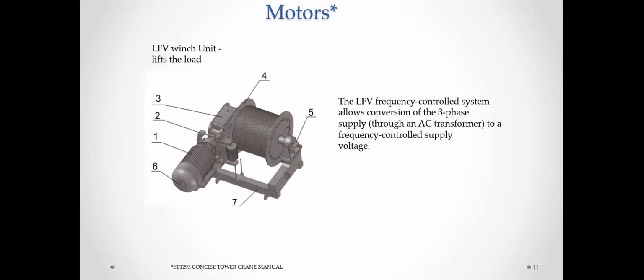Now one of the questions is which DC motors are preferred for the cranes by the manufacturers, the OEMs, whenever they create them. What I could find is that they like the DC series motors, where high starting torque is required, because the torque-speed characteristic of the DC series motors suits these frames perfectly.